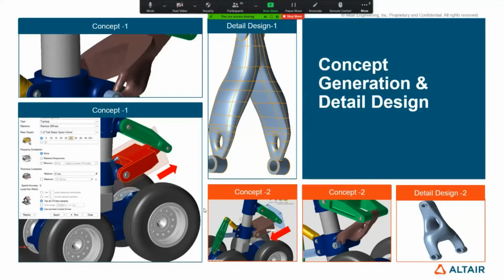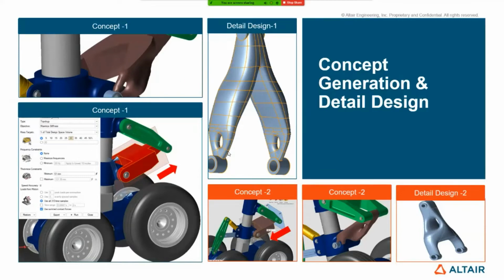Now, after you get the load, you have to go for what is called optimization. You might be asking why you should do optimization. The reason is that in most applications where a company would like to go for DFAM, design for additive manufacturing, lightweighting is a very critical aspect, for various reasons.